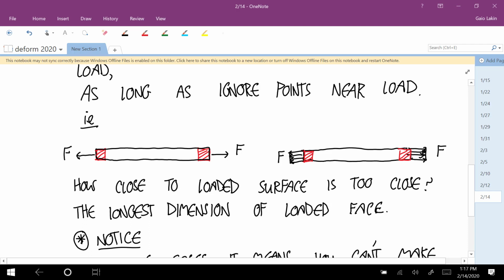And then there are other cases where most of the steel in your structure is made up by the bulk of the beam, and you don't want to worry too much about what's happening at the end. Just load up steel at the ends, put big gusset plates or whatever like they do on a bridge. If you ever look at the truss that makes up a bridge, they have thick steel plates that connect the beams together. You don't have to worry about what's happening there. All you have to worry about is whether these are going to buckle or whatever.